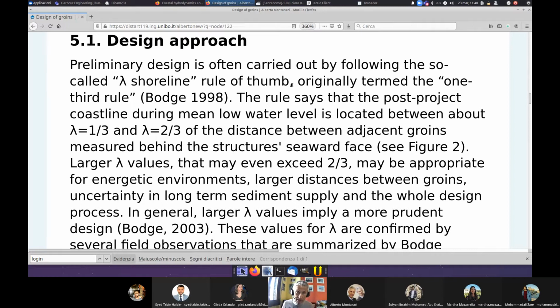As we will see when we study the shape of groins, if you want to make it high, you have to build it over a large base, and the base cannot be increased later because you have to put protections under the groin. So you have to build it already large at the beginning if you want to keep the flexibility to raise it up.